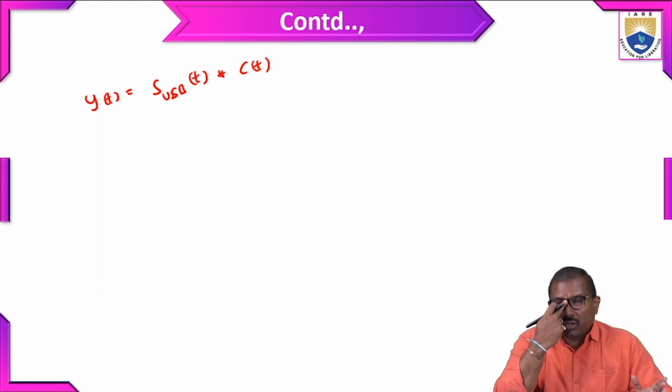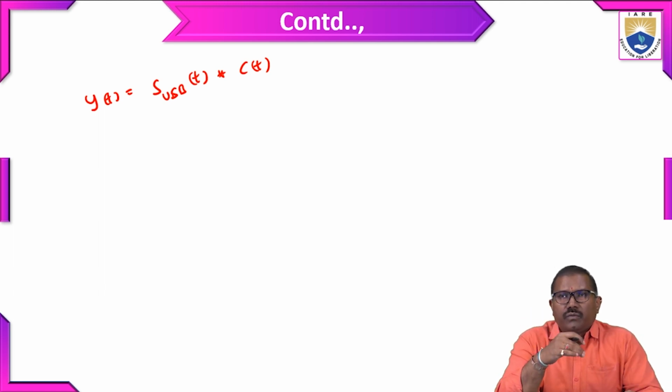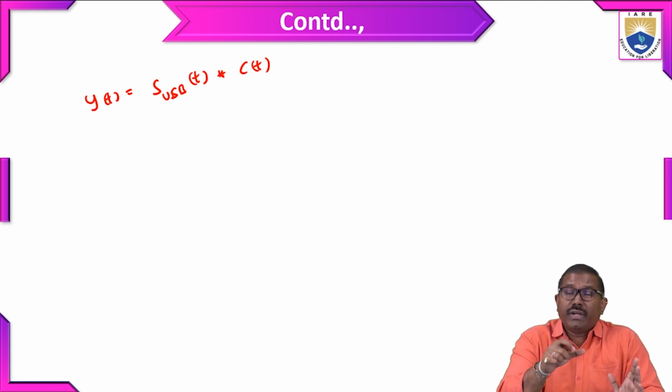So before going into this problem, first you should know the meaning of coherent. What is the meaning of coherent detection and what is non-coherent? Coherent detection means the phase information used is the same as at the transmitter. That means you detect the signal with the same phase reference that the transmitter used.